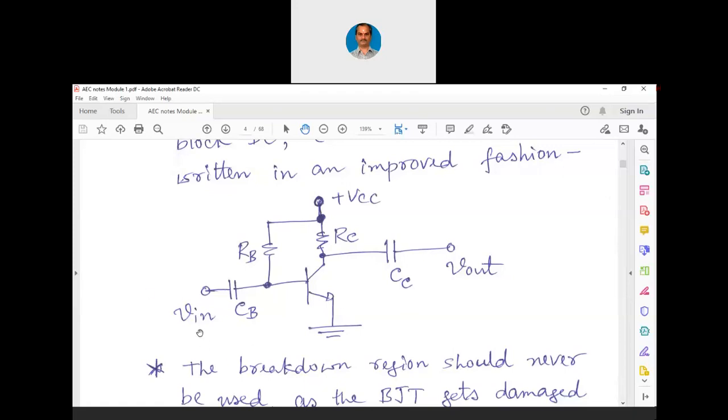So when I am speaking here, let us say the microphone is connected at Vin. Now the microphone, if at all it is connected to another transistor internally, will have another MOSFET internally. So that DC should not come here, that is why there is a capacitor here. And then we have the regular amplifier circuit.